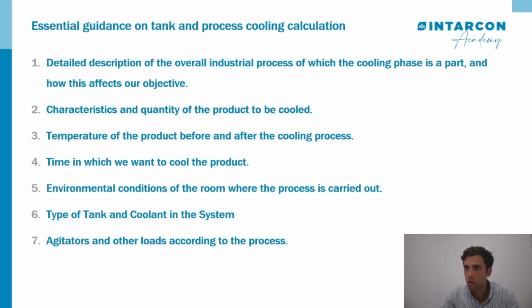And finally, the use of agitators and other loads according to the processes, such as this agitator, because we use it to promote better thermal transfer in the product. We use it to avoid cold points that could appear due to a non-uniform distribution of the temperature. So with this tool, we can avoid it.